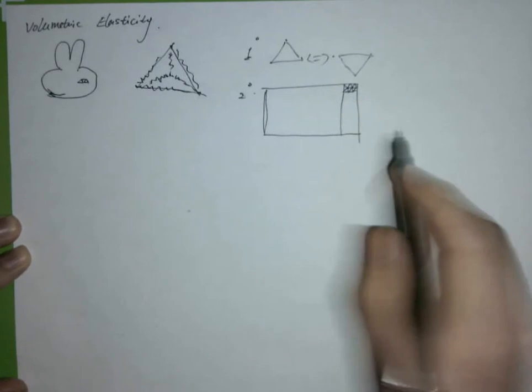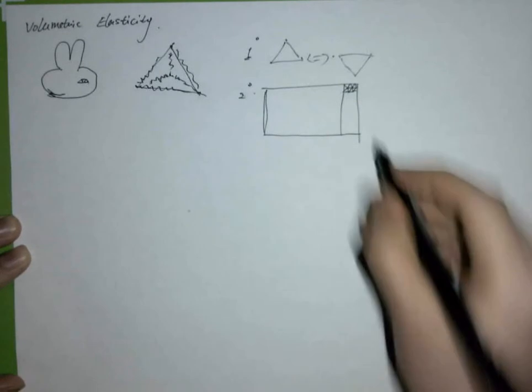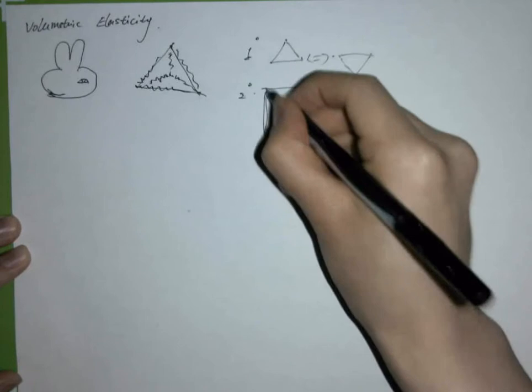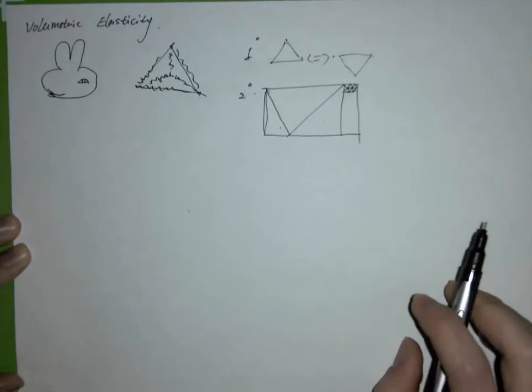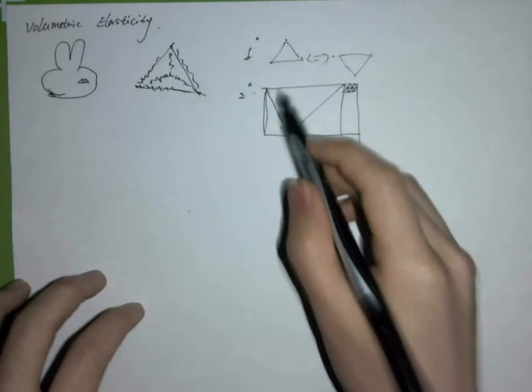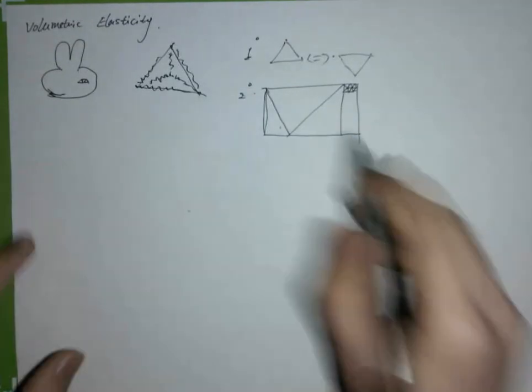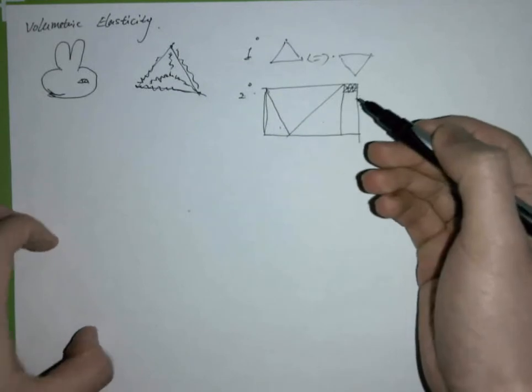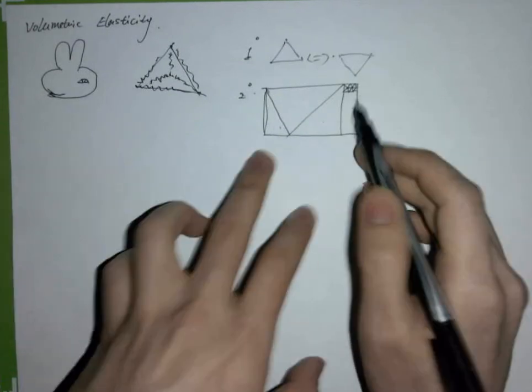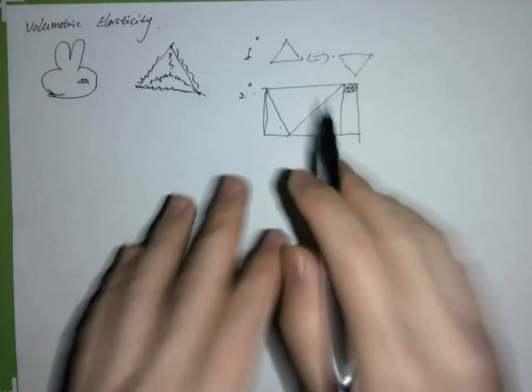But I don't really care about this part, so I'm going to just make 3 triangles out of it. And because the lengths of the springs are so different, it's really hard to determine the stiffness parameter for all the springs over here. And also the quality of the result is greatly dependent on how you triangulate this mesh.